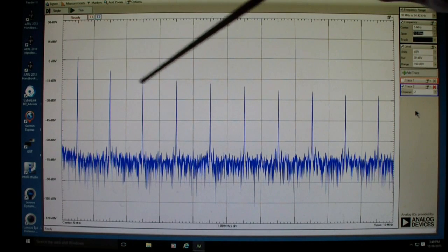So this is about the most you're going to be able to see with measurements that are reliable. We're not going to be using the analog discovery as a spectrum analyzer, in large part because most of the experiments that we're going to actually be doing, particularly in the second half in part 2, are going to be RF experiments up in the cell phone bands, around 800, 900 megahertz, and some occasionally up in the 1.5 to 2 gigahertz range.